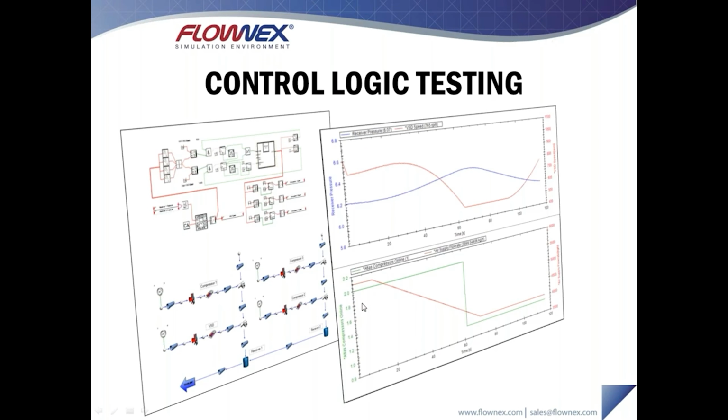In this example, what I have here is a reduction in the air supply flow rate. That's this red line on the bottom graph. We start out at a supply of about 5,500 kilograms per hour of compressed air, and then reduce that slowly down to about 4,000 kilograms per hour. This change is made over about a minute, and as a result, we can see our tank pressure begins to increase. As the tank pressure begins to increase, we see our variable speed drive decreasing because the amount of air required